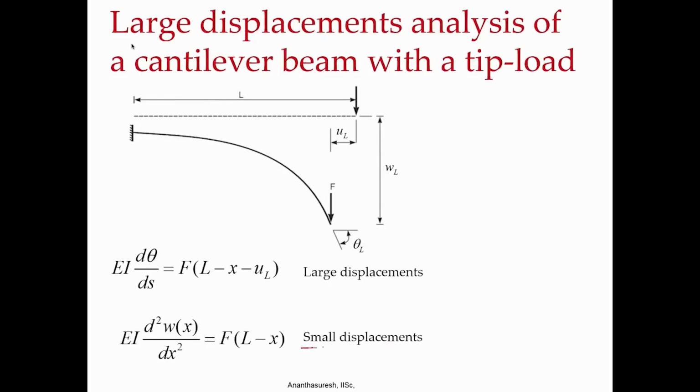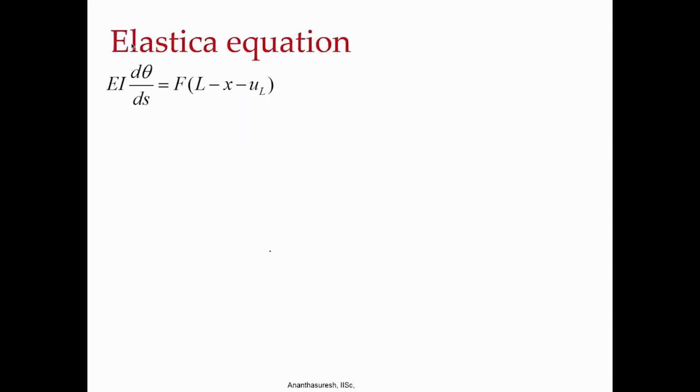So, once again these are small displacements that we have and a large displacement governing equation with a tip load, that is all we are taking, and we have this UL appearing in the large displacement case in addition to w of x. This equation is called the Elastica equation, not elastic, Elastica equation. The solution of this will be called an Elastica. So, we have E I d theta by ds equal to f times (L minus x) minus UL.